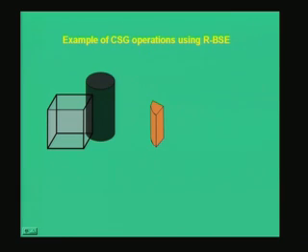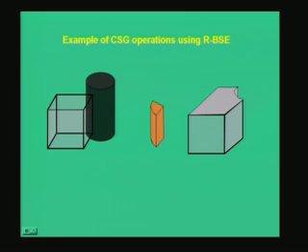What do you want to do? This is not our main aim. Our aim is to probably create this structure, which is a part of that rectangular parallelepiped chopped off, in such a manner that as if this part is missing from that structure. So, what do you do? Take a cube again or rectangular parallelepiped and position this wedge at a corner where you want to get this volume subtracted away, taken away. So, what you need to do is take this cube, put that, and then use a differencing operation. So, it is this entire cube minus this resultant structure which will produce this final structure.